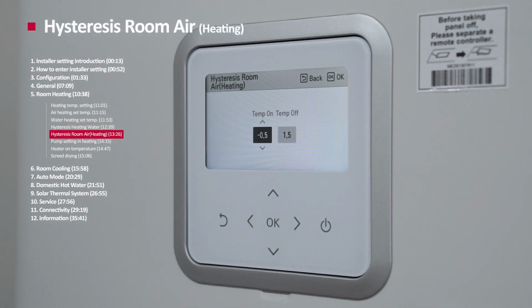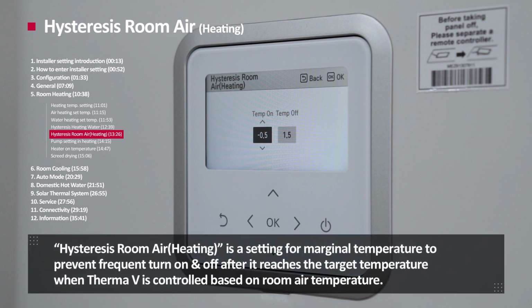Hysteresis room air heating. Hysteresis room air heating is a setting for marginal temperature to prevent frequent turn on and off after it reaches the target temperature when Therma V is controlled based on the air temperature.